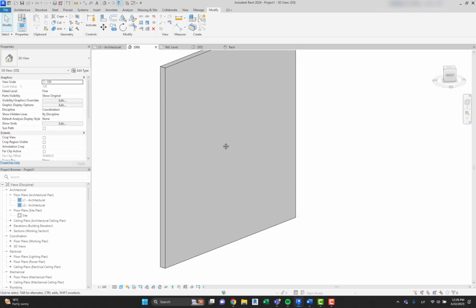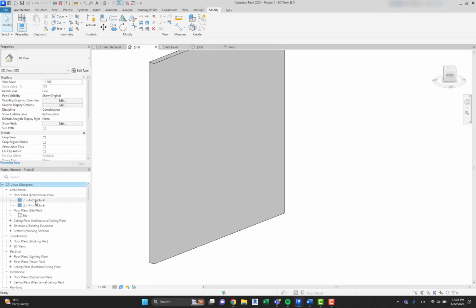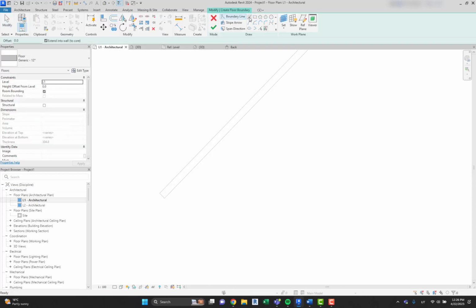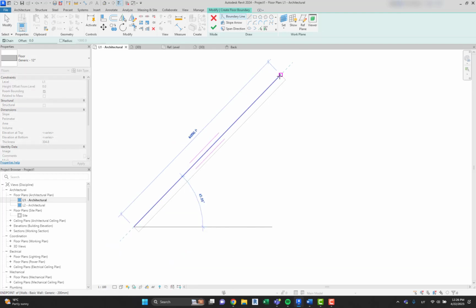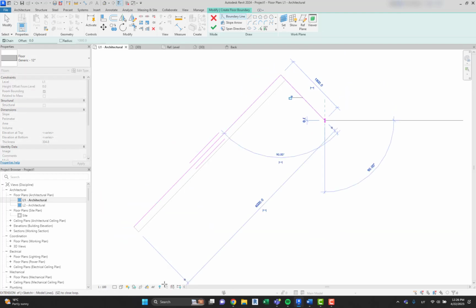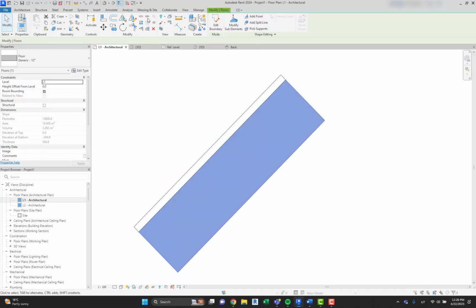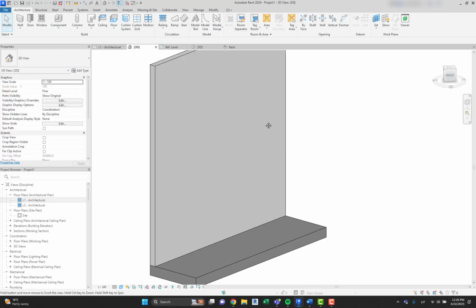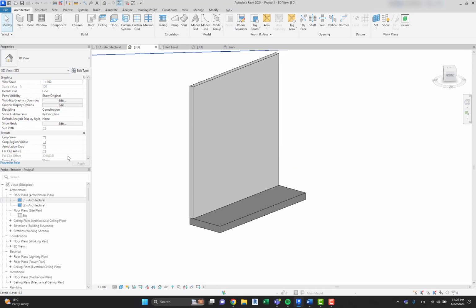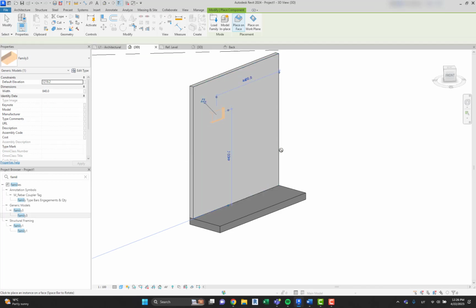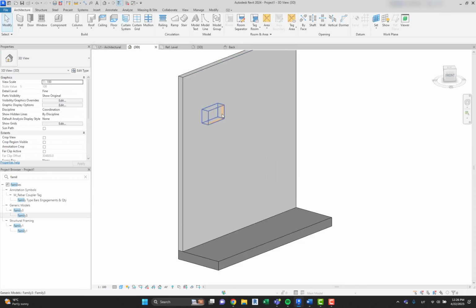Let's override the existing version, and for the sake of a better explanation, let's create additional elements, let's say a floor, and I'm gonna explain what you can achieve using that. Okay, that's perfect. Now, if I'm gonna place my created family, it's not creating a hole, right?